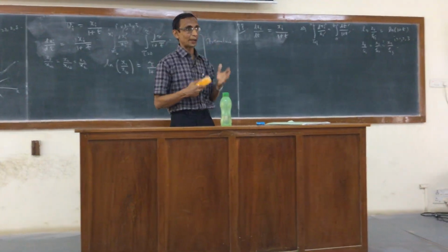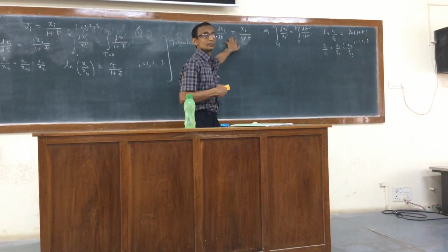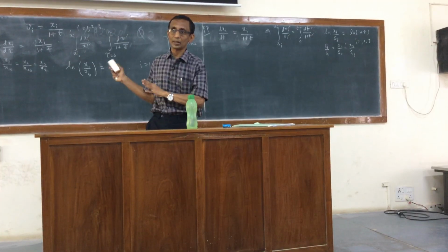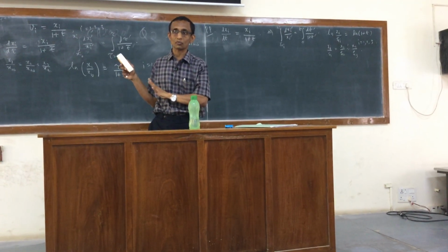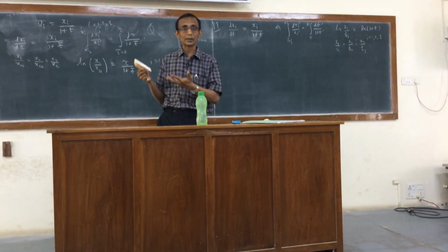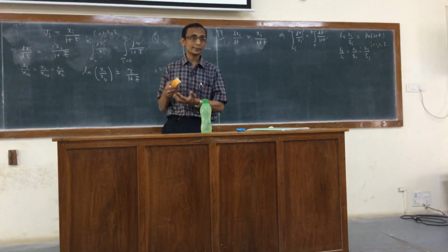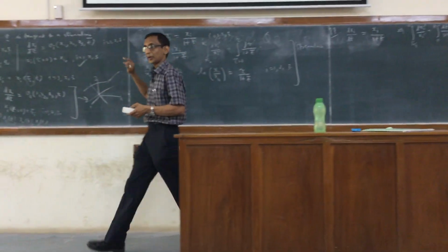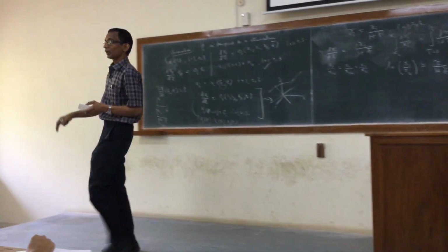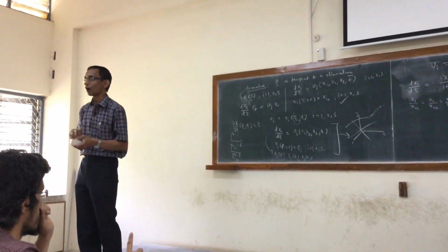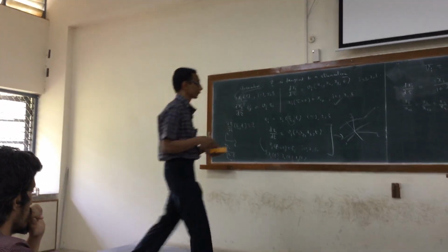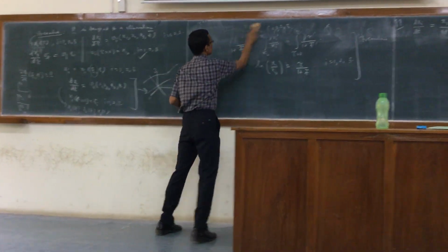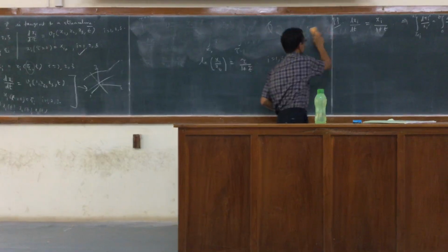So when I parameterize, I will effectively get the same type of behavior, namely straight lines through the origin. So in that sense, particle paths and streamlines in this case are the same, even though this is an unsteady flow because the velocity depends explicitly on time. It is a special case. But normally, you will probably get an example in the assignment where they are not the same.